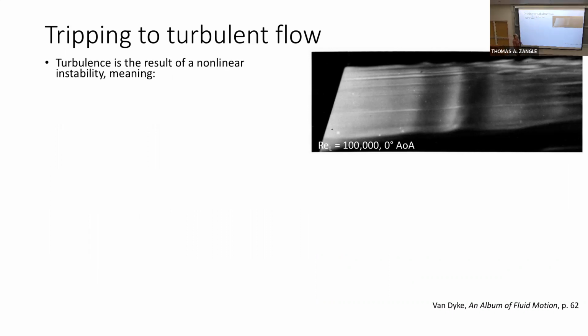Okay, so we were talking about the transition from laminar to turbulent flow last time. Roughly what Reynolds number do we see this transition from laminar to turbulent flow in external flow? Yeah, I hear numbers 10 to the 5th, also up to 10 to the 6th. So anywhere in that range, 10 to the 5th to 10 to the 6th, we're going to call the transitional regime. So that's where we see transition from laminar to turbulent flow.